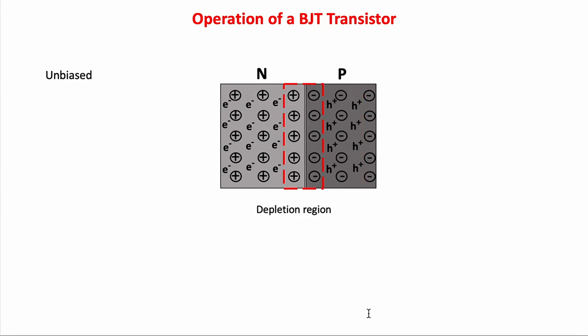All right, so biasing a PN junction. An unbiased PN junction means that we do not apply any voltage to the junction. A moderate-sized depletion region forms, and apart from the random crossing of carriers, we do not see any current flowing across the junction.